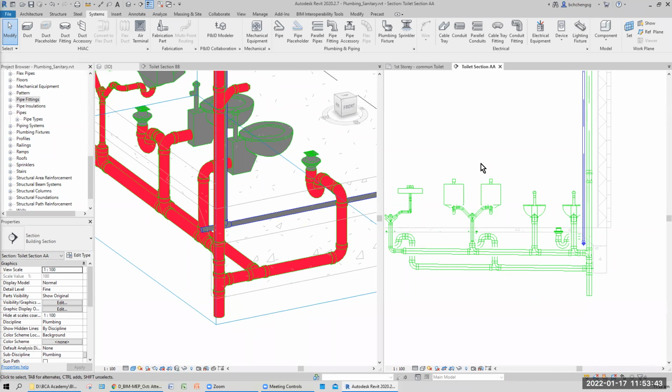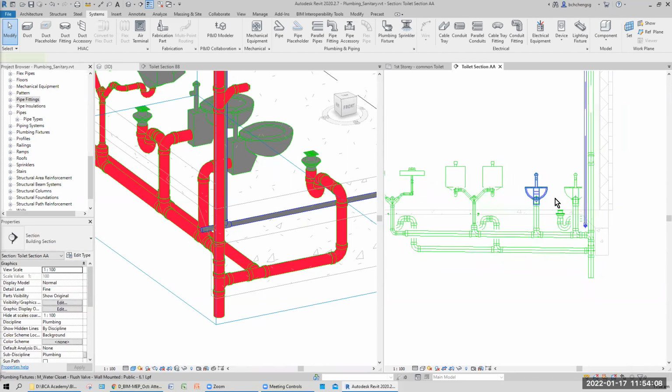Then when it's 25 mm, it distributes to your WC, distributes to your basin, distributes to the water heater, and to your shower. Now, all these will depend on the tap connection. Normally, due to the pressure, the connection is around 15 diameter. But here you need to check all your connecting points.